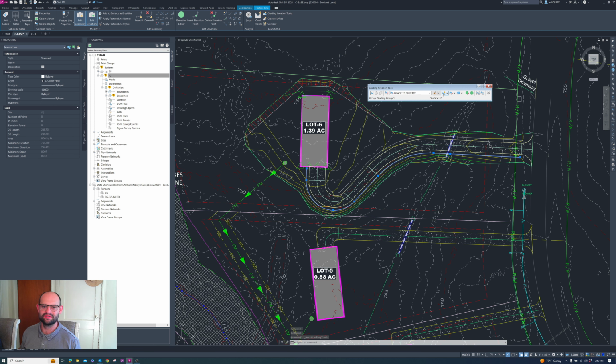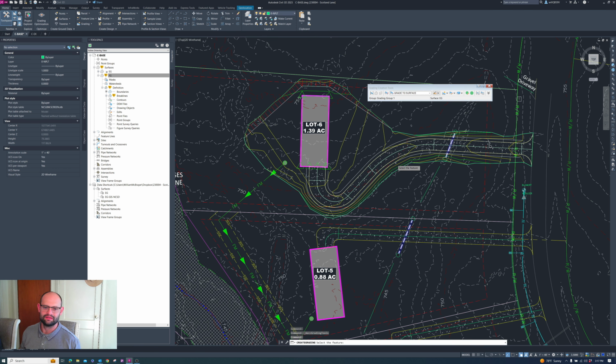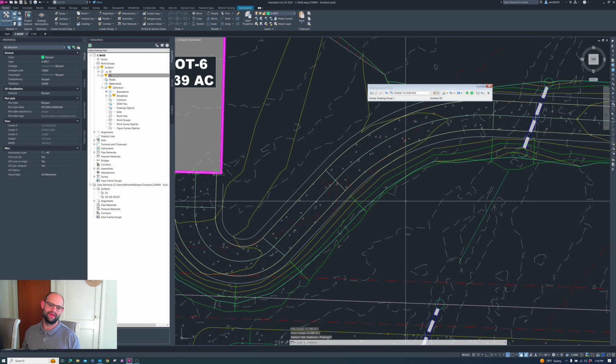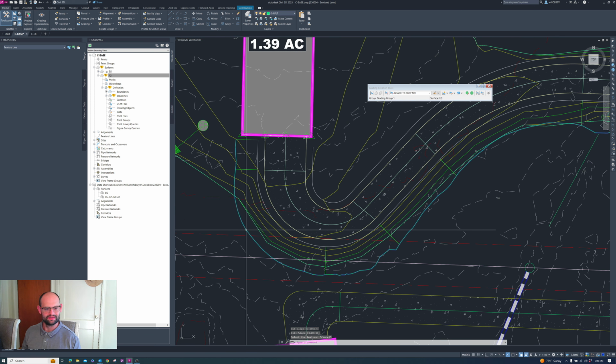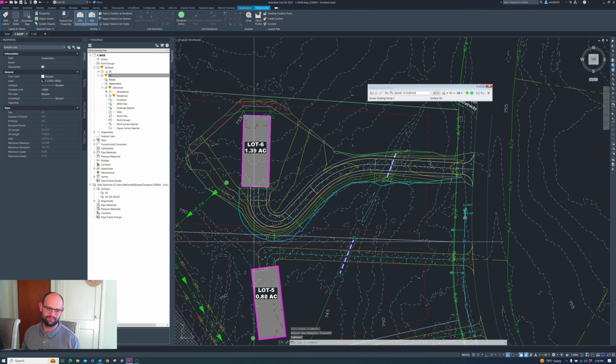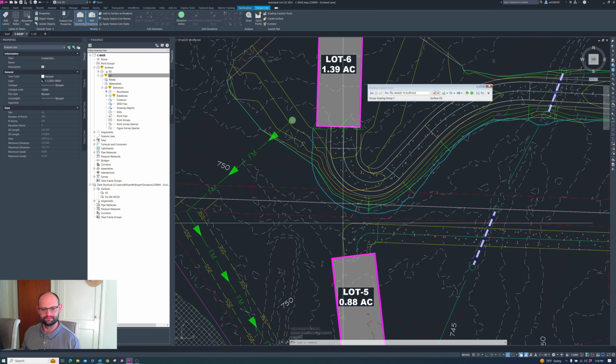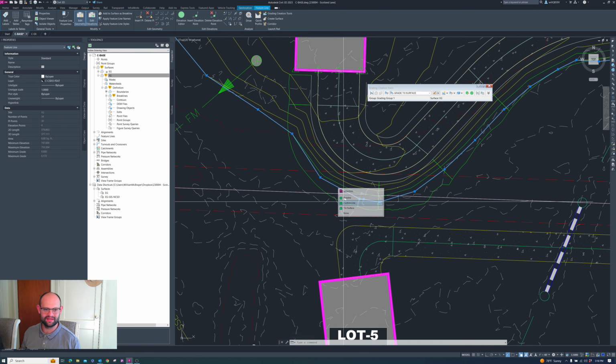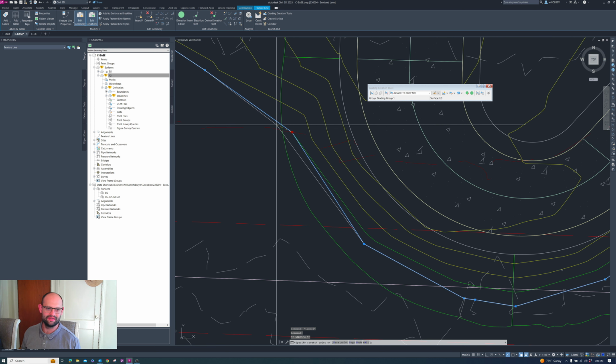Go to the surface, select the feature, click the side, tie length, accept 3:1 for the cut and the fill. Let's see where it really lands, how bad I was off. So this green feature line represents the fill limits. Let's move our feature line to be just outside of that at the key locations.